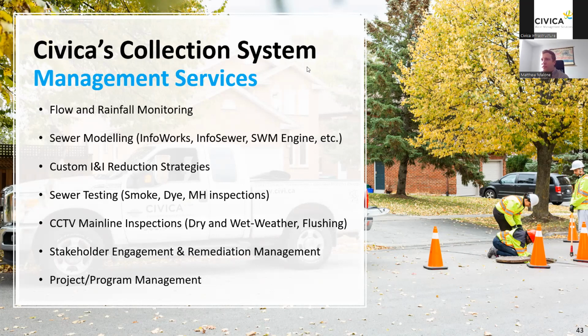How large have you custom made the flume inserts? What pipe size? So I know in the past we've done some big pipes like 1200, I want to say, millimeter. We don't typically recommend too big, or we don't use flumes in a lot of large pipes.